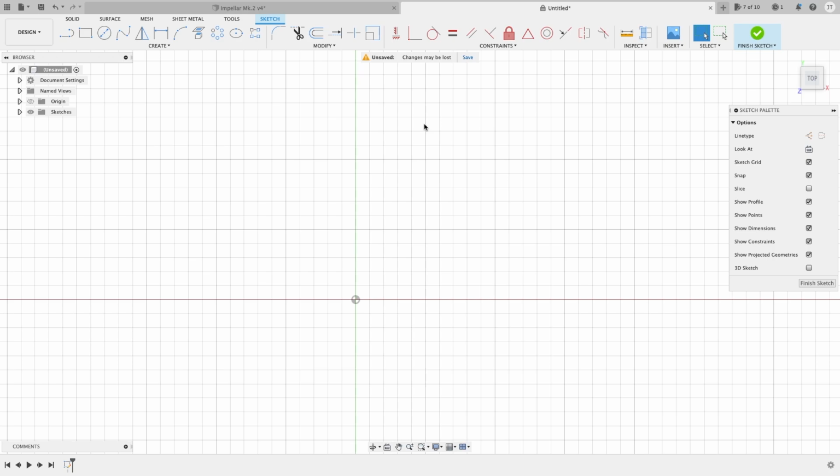Basically, a constraint is a piece of your geometry that is in a fixed location. It is bad practice to create lines that are not tied down to something, because if you want to change something later on down the road, it could throw off the geometry. If you change a shape and it's not connected and planted in place, it can cause some serious issues with your design. So constraints are very important in keeping everything tied down to a central place.